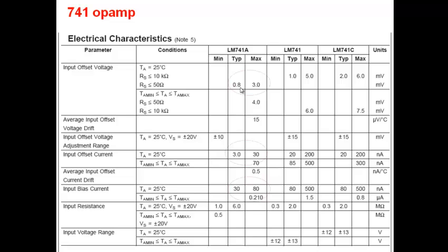I mean, who designs one circuit? If you have a product in mind, you're fabricating and selling, if not millions, lakhs or thousands of such circuits. So when you design, it doesn't work for only 2 nanoamperes of bias current. It has to work for the whole range.